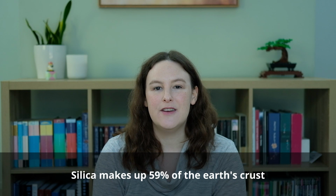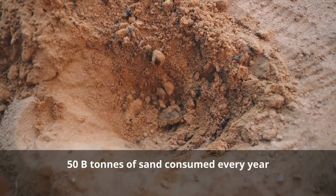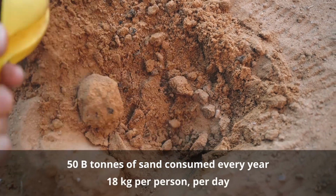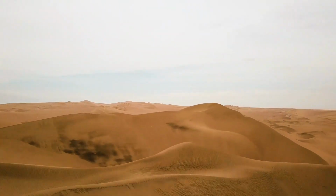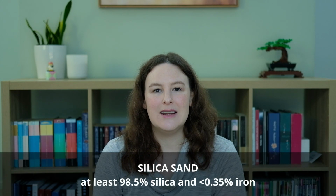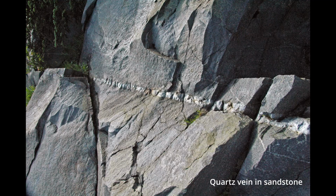Silica is seemingly an exceptionally abundant resource, making up a whopping 59% of the Earth's crust. It's the principal component of sand, the world's most consumed resource, with 50 billion tonnes consumed every year, an average of 18 kgs per person per day. However, not all types of sand are suitable for industrial purposes. Desert sand, for instance, is largely useless due to its smooth grains and high impurities. Glass production requires high-quality silica sand, composed of at least 98.5% silica and less than 0.35% iron. While coastal dune and riverbank sand are sometimes used, the most common source of silica sand is quarried quartz-rich sandstone.